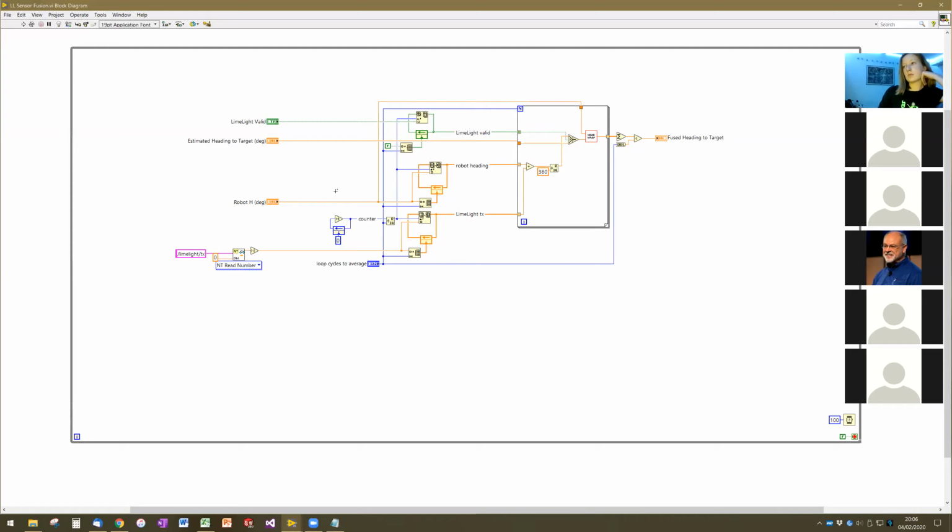We don't have another sensor giving us information about how much we've moved closer to or from the target. All we have is the estimate and the LiDAR range. Whereas in this case, we have the estimate, the camera angle, and the knowledge from the IMU about how we've behaved in the interim period of time.